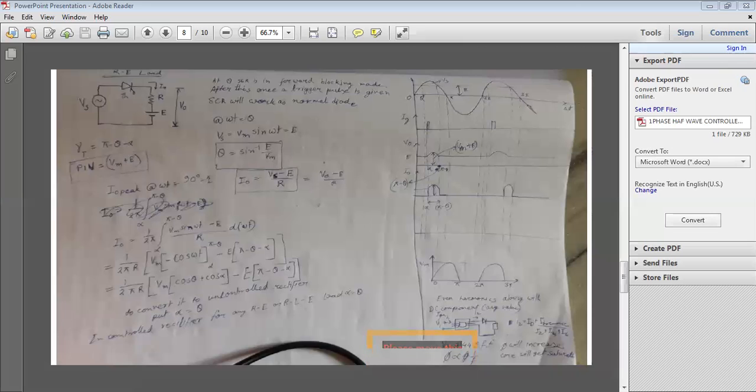If we apply DC to a transformer, what will happen? If we apply DC to a transformer, the frequency will be zero, since flux is inversely proportional to frequency, and flux will be too high, the core gets saturated and the winding will be burnt. These are the difficulties when we get the DC components or even harmonics. Okay, so we are having a full wave converter.